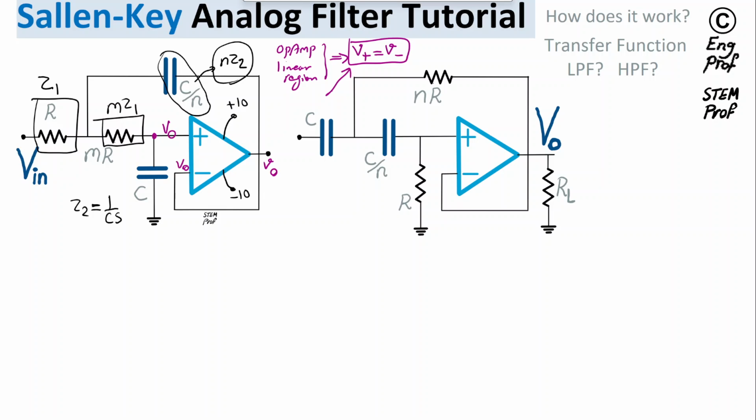One thing before I write the analysis, which is a quick one, intuitively speaking, when you look at this topology of Sallen Key, when the frequency is very low, close to DC, or even at DC, s is j omega, and omega is 0 at DC. Therefore, at DC, obviously, denominator is 0 for the cap. Impedance of the cap goes to infinity, or cap is open. So that at DC, in this topology of Sallen Key filter, this is open, and as a result, there is no current that can flow through the input terminal of the ideal op-amp, because practically it has infinite impedance.